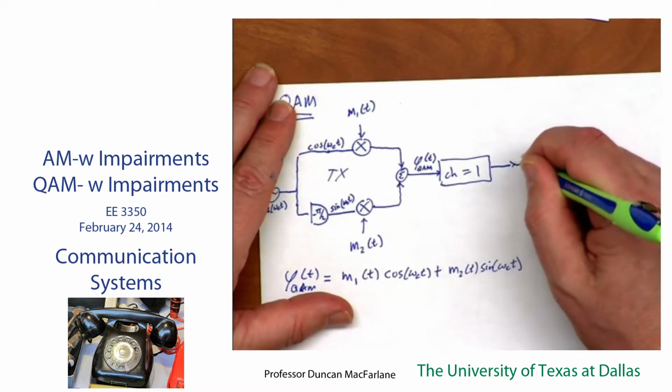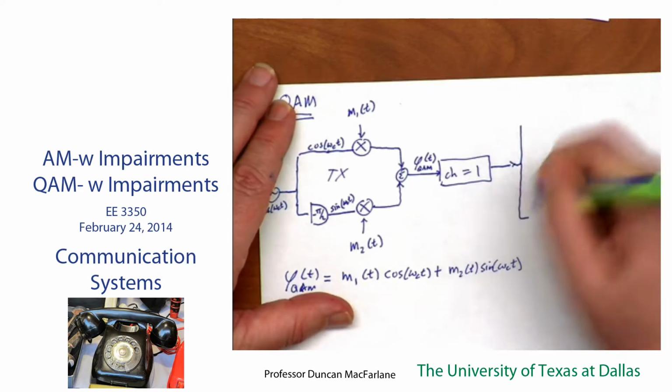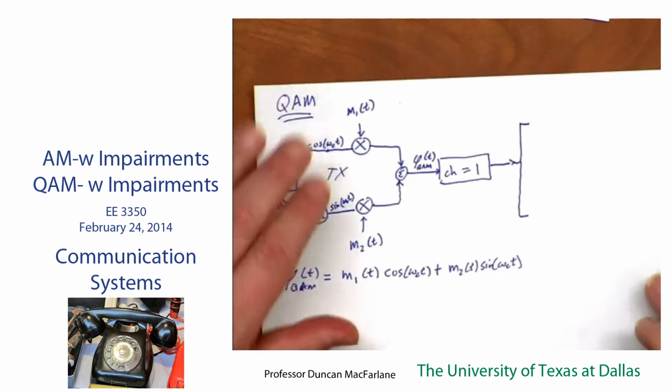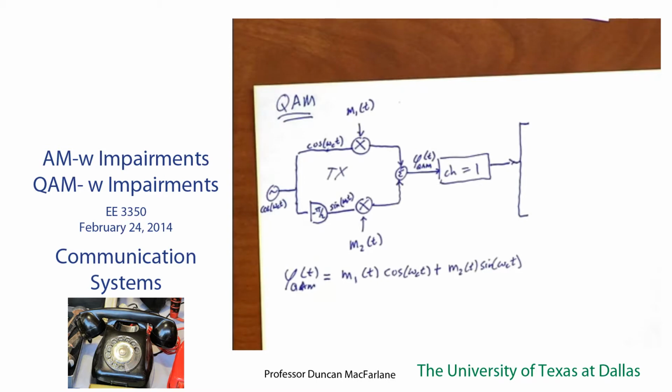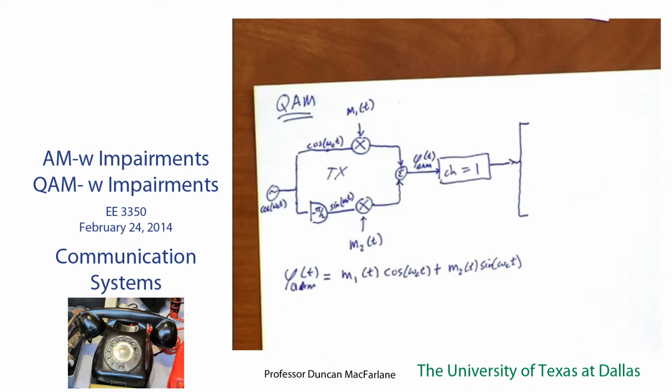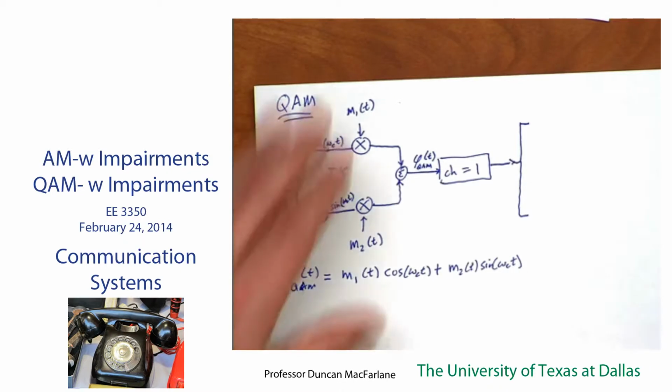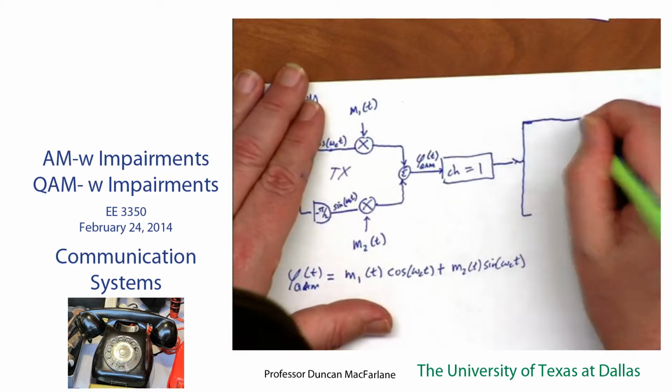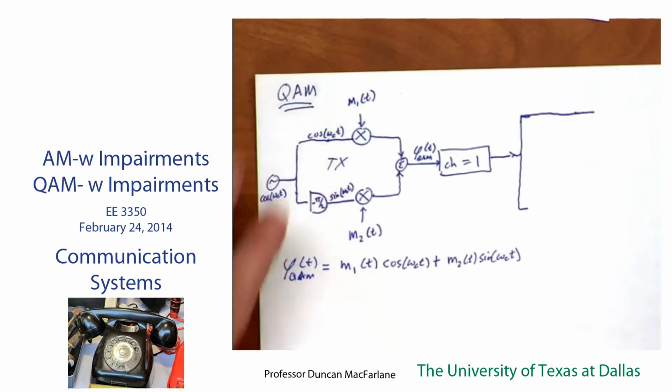So now on my receiving end, I'm going to use a coherent detection. Especially motivated to do that because the phase between this guy here and this guy here is what makes this thing work. So I have to keep track of that. Quick question. So coherent detection keeps track of the phases. So coherent detection is when I use a local oscillator.